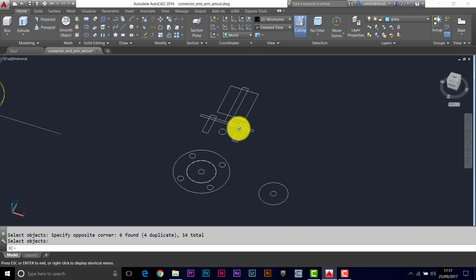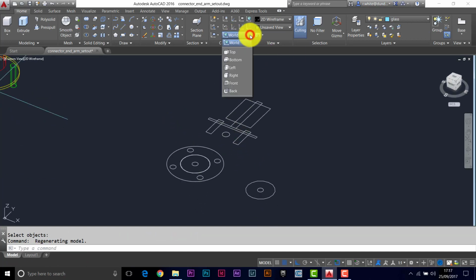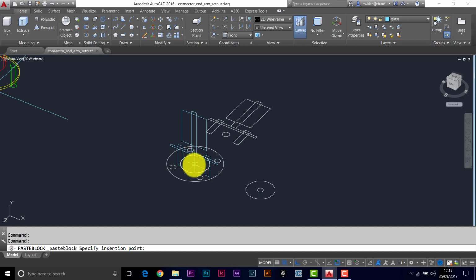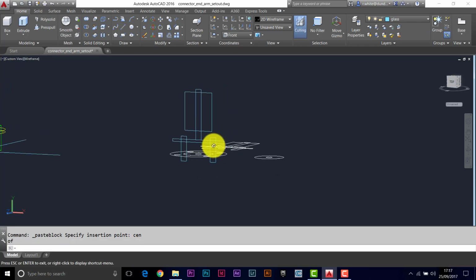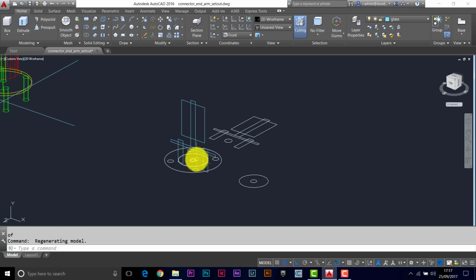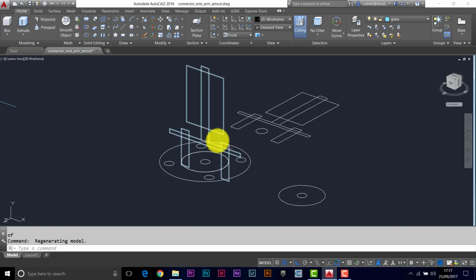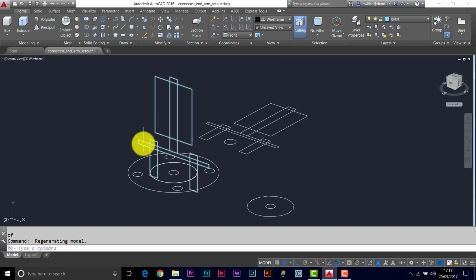Okay, flip into 3D, change to the front coordinate system, and then Shift Control V to bring it in vertically now. We'll use the center point here as the insertion point, and that should give us the relative heights that we need to move objects to, and then give them some solidity. I think I'll keep this as a block because it'll make it easy to delete later on.